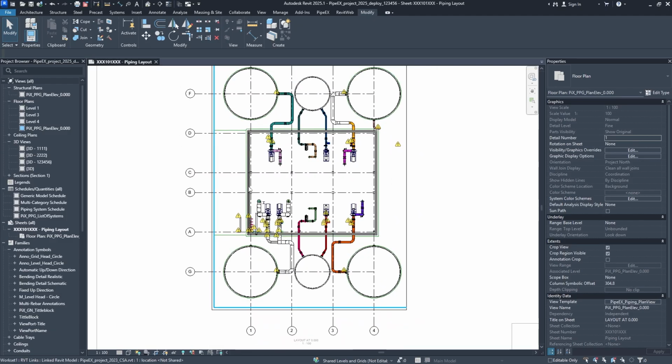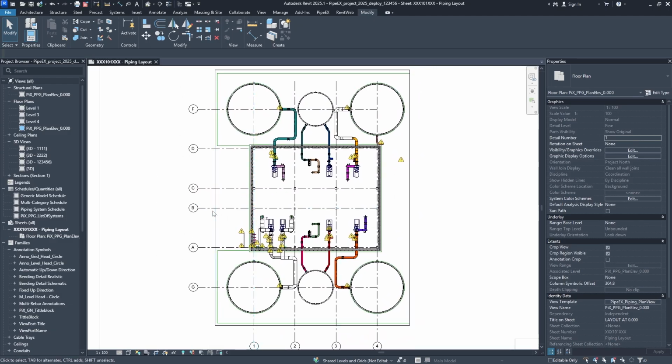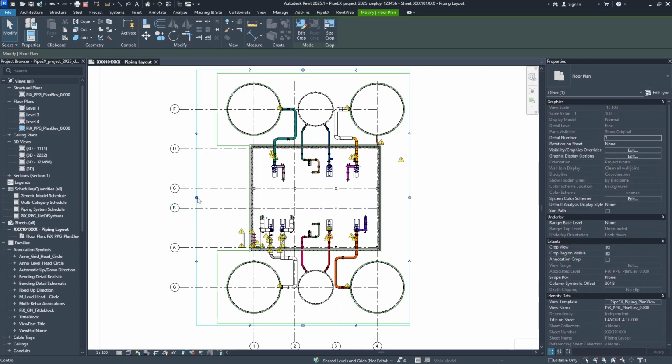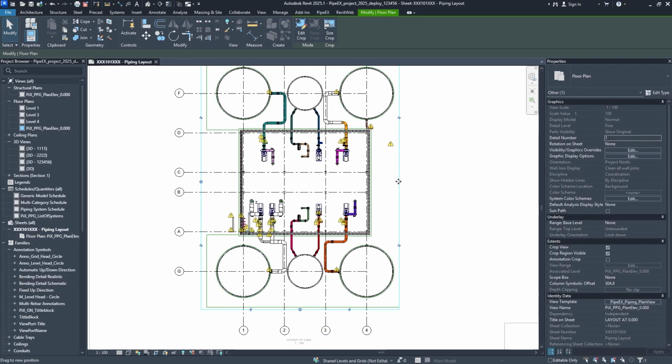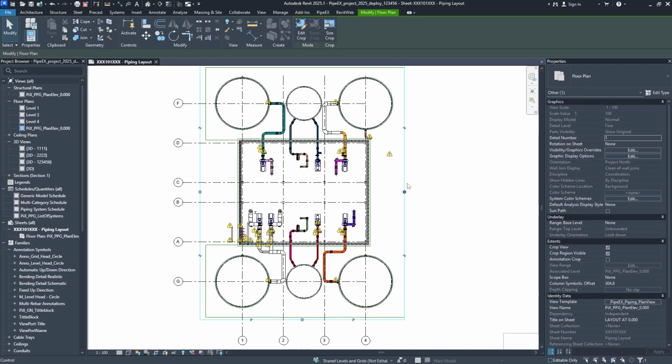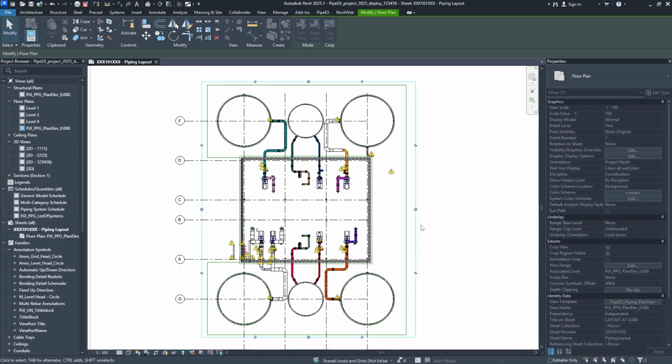I would always recommend you to use monitoring or sharing, or to copy the grids from the civil model, because then you have a little bit more flexibility in how you can adjust them. As you can see now, when I adjust the regions of the viewport, the annotation also shifts in one go. If you keep it not imported, then it will not be that adaptive.